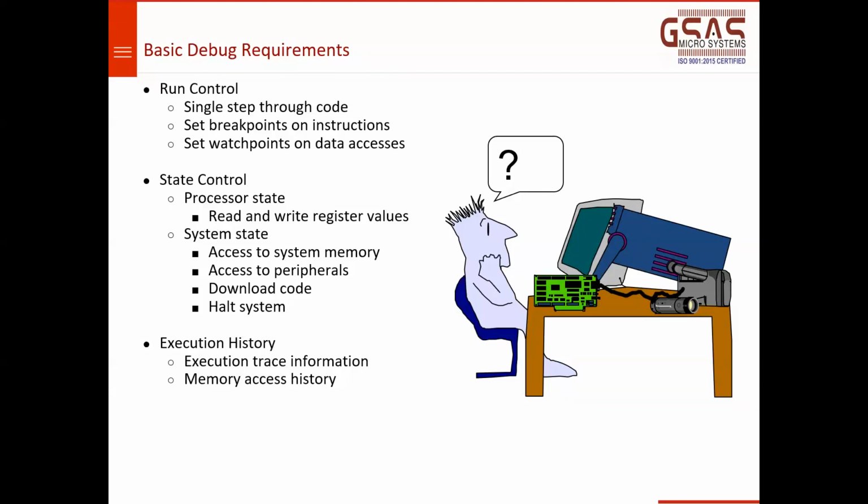So for a basic debugger, what do you require? You should be able to do run control, that is, you should be able to single step through your code. Single step in the sense statement wise, one by one, you should be able to execute the code. Second thing, to put a breakpoint on instructions.